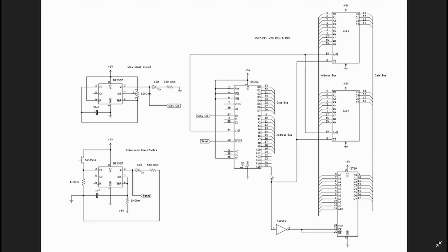So first, the chip select. We've got two chips we want to select with RAM or ROM. The A15 address line, when it was high, was going to select the ROM chip, and when it was low, we wanted to select the RAM chip. So here, if it's low, we just come straight out and it's chip select. Remember, its enable is low, so we're good. If we're low on the A15, it will select it. If we're high, chip select is still low, so we need to go through a NOT gate. So that's what that's doing, going through a NOT gate if we're high on the A15.